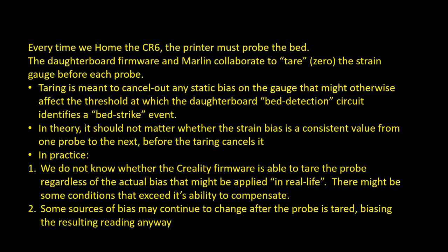So you have to run G28 anytime you've switched the machine off and back on, and at the end of a print you might pull the bed forward to pull the model off. You might push it back. They don't know what you've done because there are no sensors that tell them if you've moved the bed or the gantry. They don't know. So they insist on G28 before print in order to locate themselves reliably within 10 microns of the bed, and so on, 20 microns. So in all fairness, we need to let them do that, but that means we're exposed to